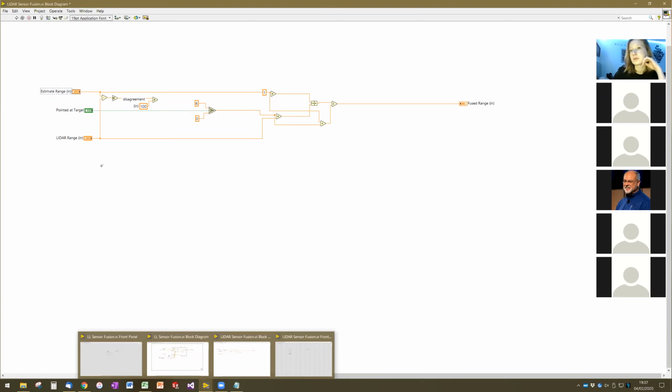If we had, for example, an IR range finder that told us if a robot was close, then we could use that to incorporate our decision about whether or not to trust one sensor more than the other. So we could add sensors or intelligence to the robot in order to make this decision even better. Again, there's not really a right answer. It's always a guess, and you're just looking at what is the most common failure point in a given situation with the information that you have, in order to guess which sensor is wrong.